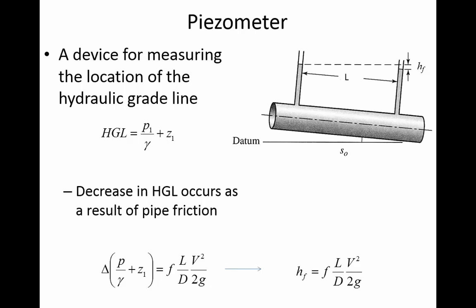In a big pipe, all this flow is pretty far away from that edge of the pipe wall that's imparting resistance, whereas when you've got a small diameter pipe, the entire cross-section is in pretty close proximity to that perimeter where the pipe is holding back the movements of the liquid. So that's a little exploration.